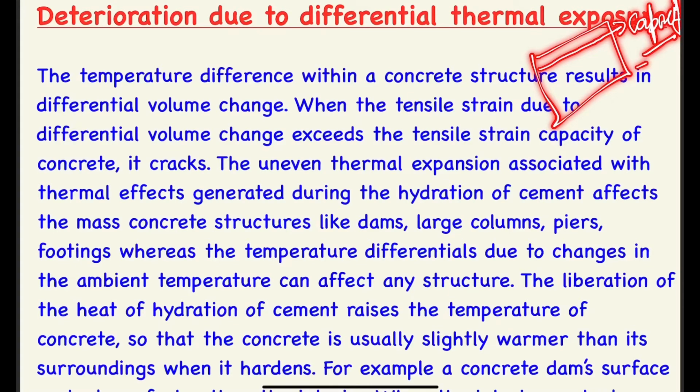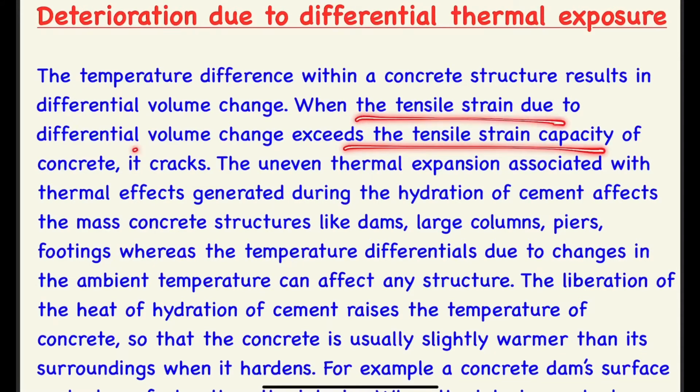So what this point is telling here is that when the tensile strain due to differential volume change exceeds this capacity, it cracks. Please go through this point. This is a very important point.